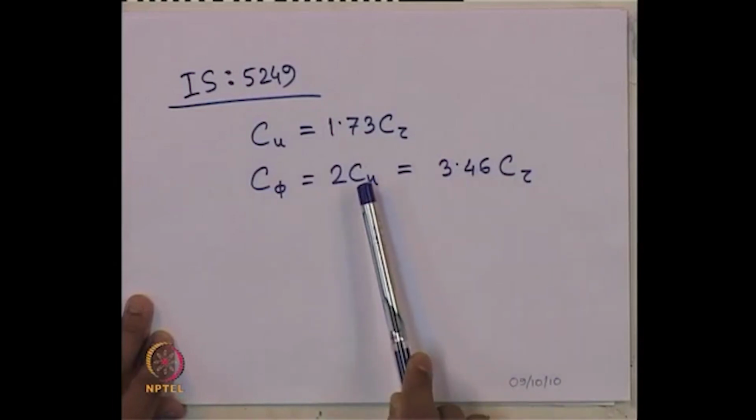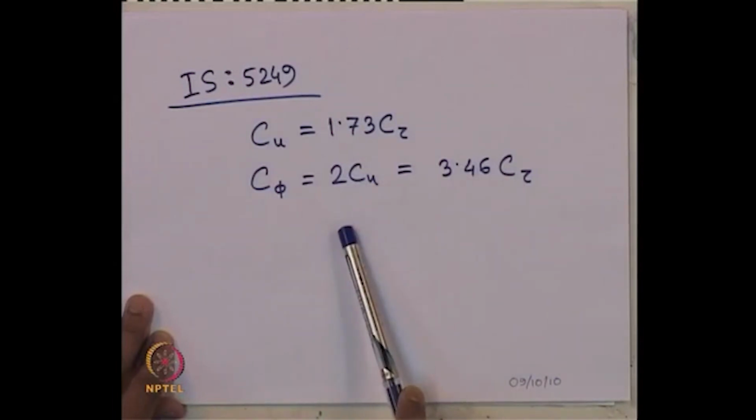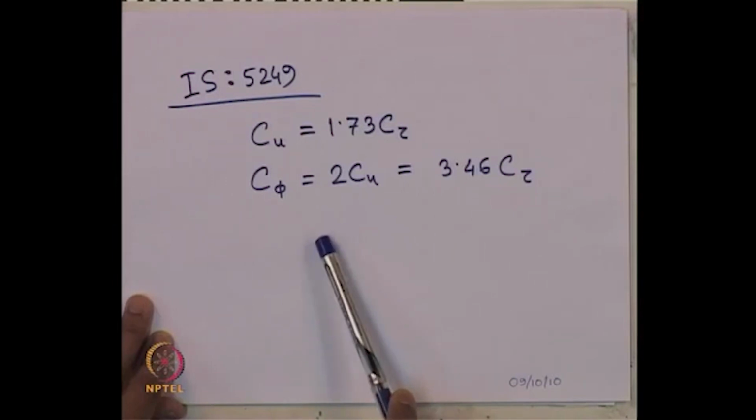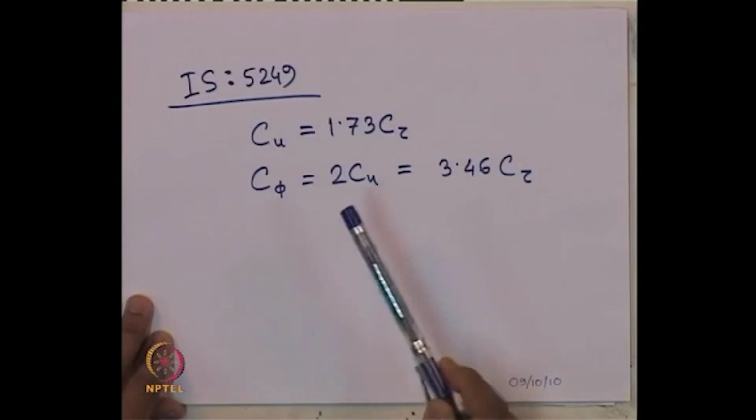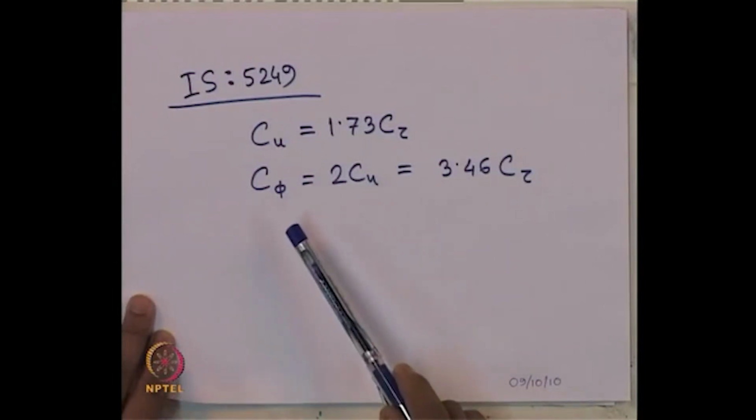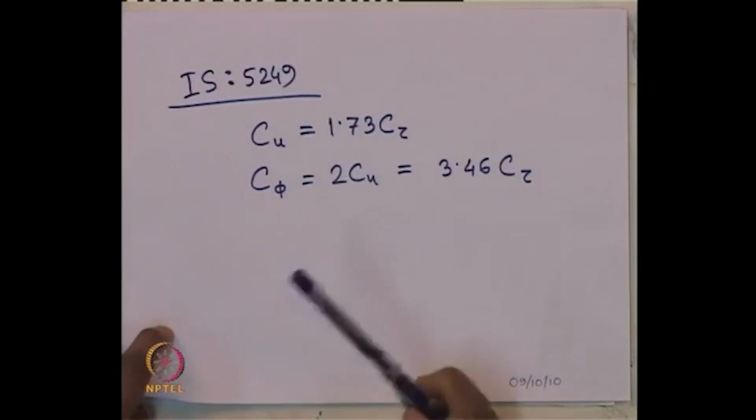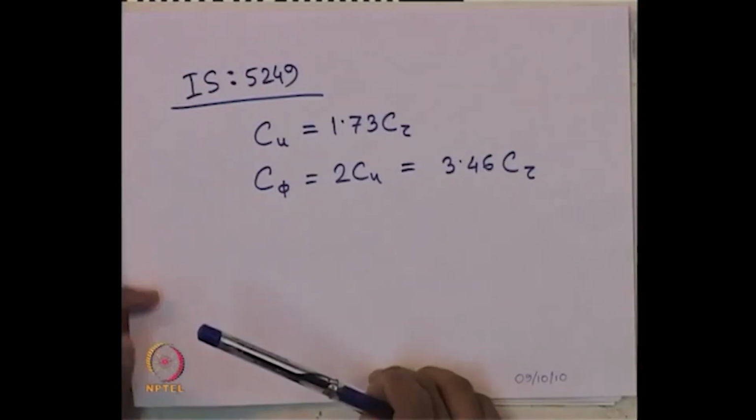And why is it required? Once we can compute these coefficients, we can get the corresponding stiffness, whether kz, kx, k phi or k psi. That can be used in our expression to compute the natural frequency, the displacement,